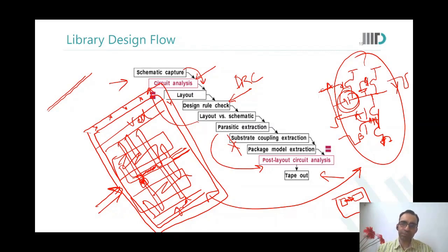As you have mentioned, we consider the effect of parasitic extraction in the post layout circuit analysis. So after considering, if we see that there is some effect, then we again go to the previous step and consider this effect before taping it out. Yes, then we go back to the circuit stage, the schematic stage. We say that I want to increase the size of this particular NMOS because the output capacitance is very large. The NMOS size that I have put yet will not be able to drive sufficient current and give me the timing that I am looking for. So I increase the size in the schematic. I then change the layout. I then again do DRC, LVS, again extract, and then resimulate. The entire loop has to be done again.